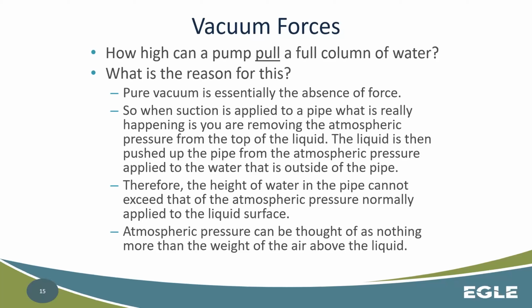So if I no longer use vacuum forces by putting my pump over the water and trying to suck water towards me, but instead place my pump in the water and use pressure, well, now the water to be pumped can essentially reach as high as we want. But with a vacuum, you can only go as far as atmospheric pressure.